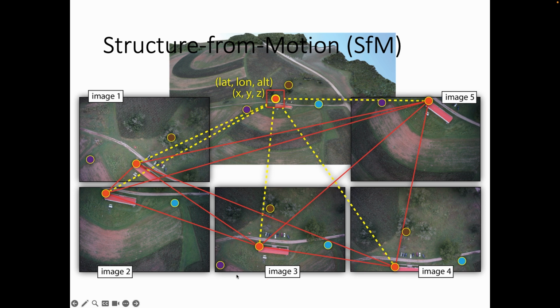So I've got here just an example of a bunch of images, and we're going to use information in those images and tie those things together in order to extract real 3D locations in the real world. Now, just the images by themselves won't be able to give us that. We'll need some additional information about either ground control points or maybe GPS coordinates of camera positions, something like that. But given that information, we'll be able to take 2D images and turn them into 3D information.